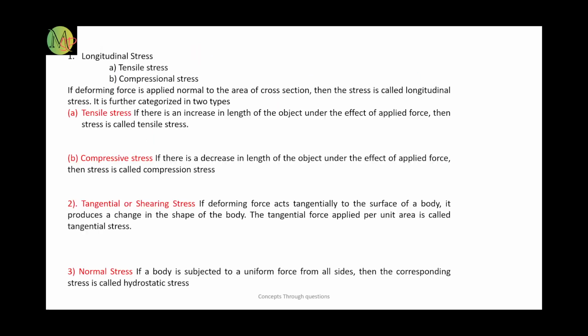Clear? Yes. Next, there are different types of stresses. First one is longitudinal stress. Longitudinal stress is classified as tensile stress and compressive stress. Now what actually is tensile stress? A tensile stress always tries to increase the length of the body. See here, this is the tensile force. F is known as tensile force.